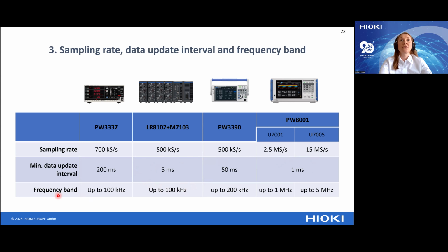We have also different frequency bands. Then again, looking into the application, are you looking into lower frequencies? Then maybe a power meter is more than enough with 100 kilohertz, or a data logger in that sense. Or are you looking into higher frequencies analysis with a power analyzer of up to 5 megahertz.